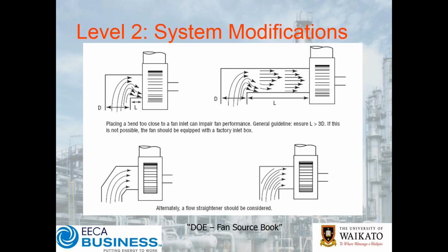It's not uncommon to see cyclones jump up and down vertically, sort of 25 or 50 millimeters. All because the duct design and the airflow hasn't been engineered correctly. So if you do have to have a duct really close to the fan, you want to think about what we do to ensure that we get good airflow coming in. So whether we change the duct on the bottom left there, or do we need to put some flow straighteners to help the flow come around these bends.